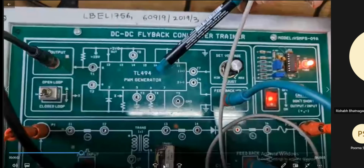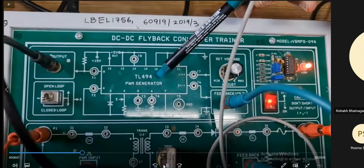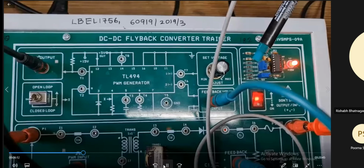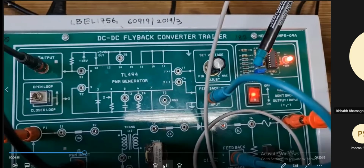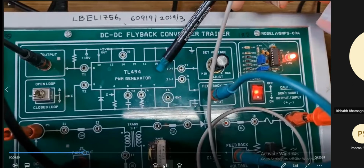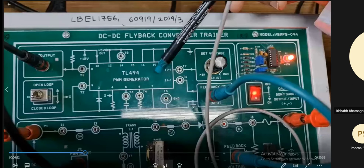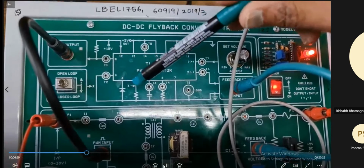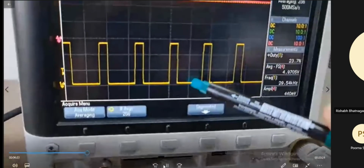This TL494 is an IC which internally has a triangular ramp generator, and we can connect the controller. The controller essentially generates a reference voltage, and the internal comparator compares the reference voltage with the triangular ramp and generates the suitable duty ratio. So the PWM duty ratio signal is what is seen here on the scope.